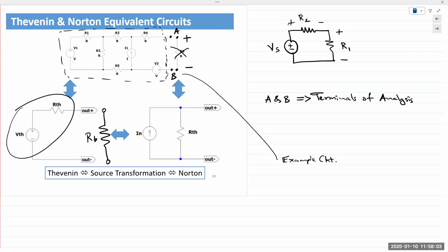You have a circuit, you can take any component in the circuit and you can say, determine the Thevenin and Norton circuit as seen by that component. Then you simply remove that component from your analysis. You got those 2 points. Now that is the circuit you need to analyze. And that is what I will ask you to do. Not any analysis, not any questions, just draw the circuit diagram. Okay. This is just to get you prepared for what's coming.